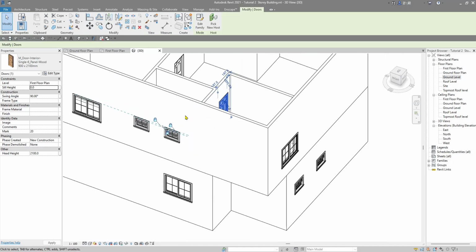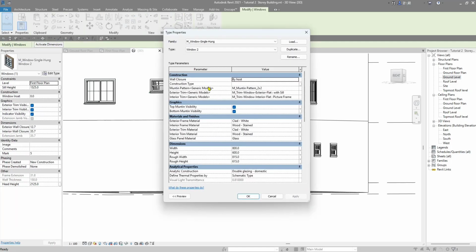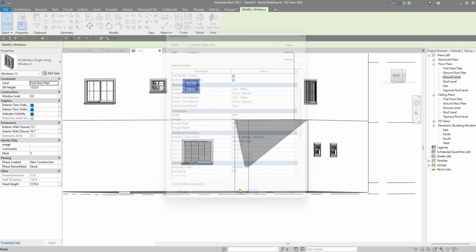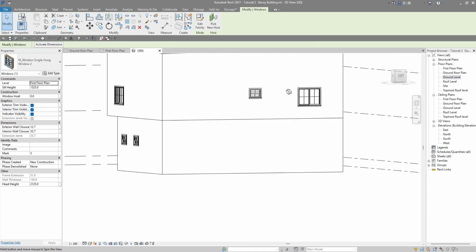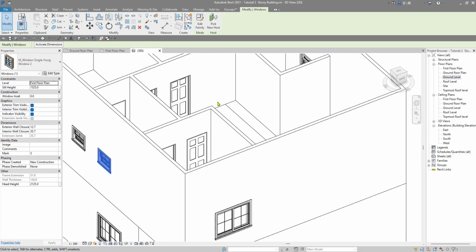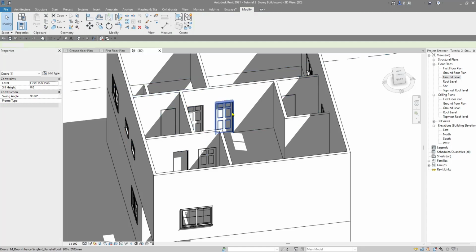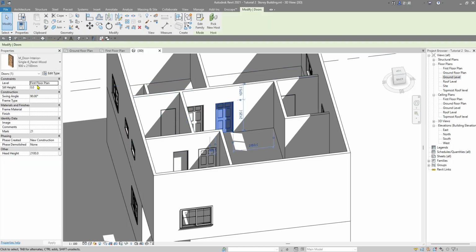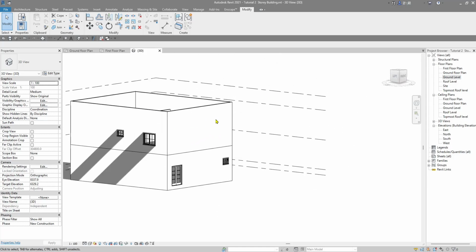It's because we've locked up our windows with the door, so it tends to move everything we locked up down. But we just fixed the problem. We just clicked on the door, and when you check the base constraint, it says negative 200 because I reduced the dimension of the window. So I just changed that to 0, and it moves up, and it moves up also with every single thing we locked up and aligned with.